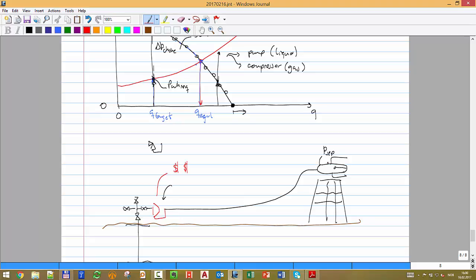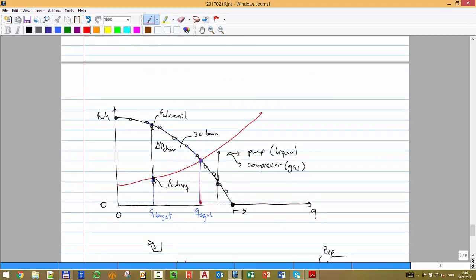The choke is a standard component, so I can achieve really any rate below the equilibrium rate by choking, no problem, it's already in place. But if you want to go to the right side of the choke, it's like going to VIP. You have to pay, and that pay is the compressor or the pump. You need something that will create, in the opposite direction, the pressure drop.